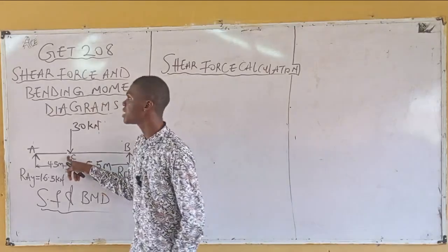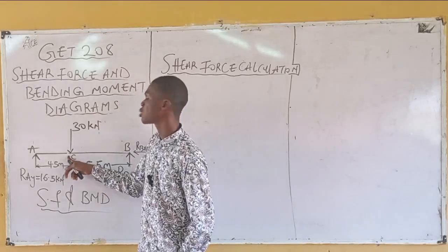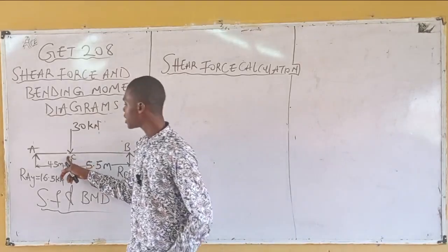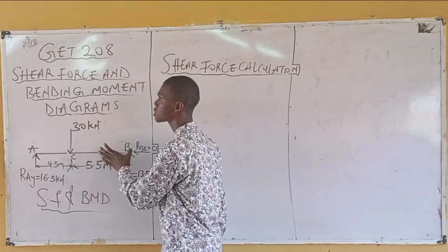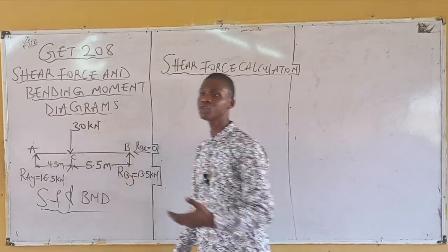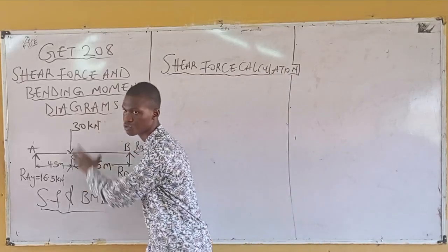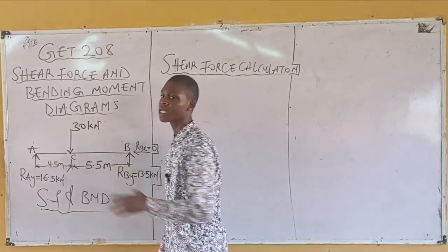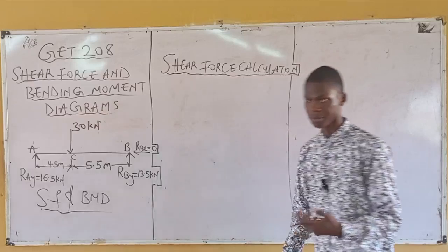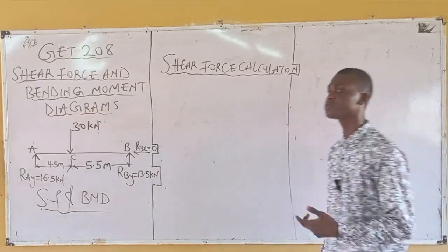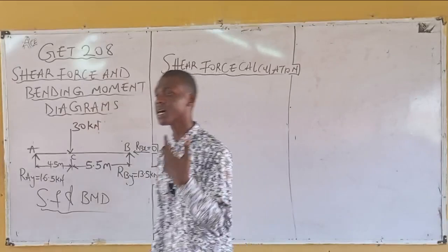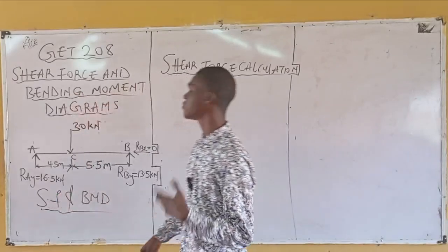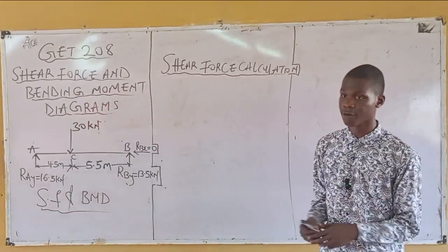So now, let's say I'm having RCX equal to 20 kilonewton, meaning these two horizontal forces. I'm using vertical forces to plot the shear force diagram, right? Now, these two horizontal forces, can I use them to plot a diagram? And the answer is yes. The type of diagram is called an axial diagram.